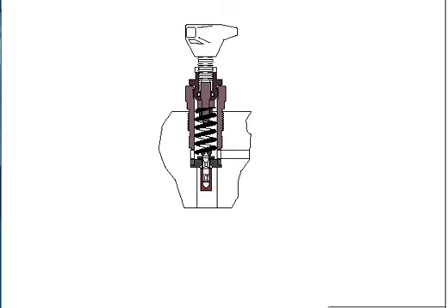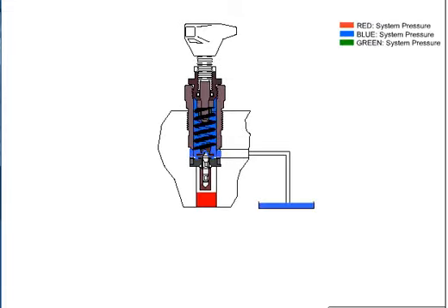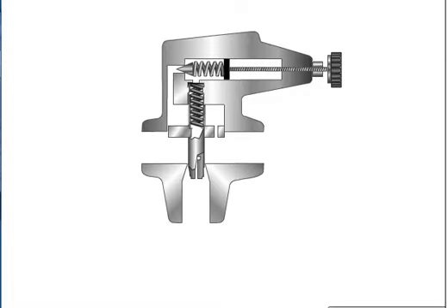It should be noted that direct-acting relief valves are usually available in only relatively small sizes because it is difficult to design a strong enough spring to keep the poppet closed at high pressure and high flow. Pilot-operated relief valves are designed to accommodate higher pressures with higher flows, being confined to a smaller frame size than a direct-acting relief valve with the same rated flow capacity.